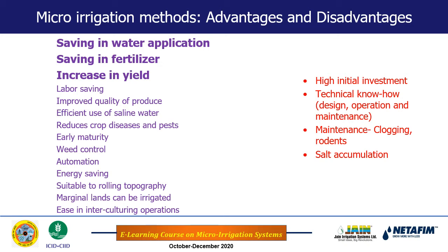But in the case of the drip irrigation system, as we can maintain the water at low tension or at high water content, even if there is saline water and the salts are accumulated in the root zone up to a certain level, the roots won't find difficulty in extracting that water, because water tension is low in the root zone.